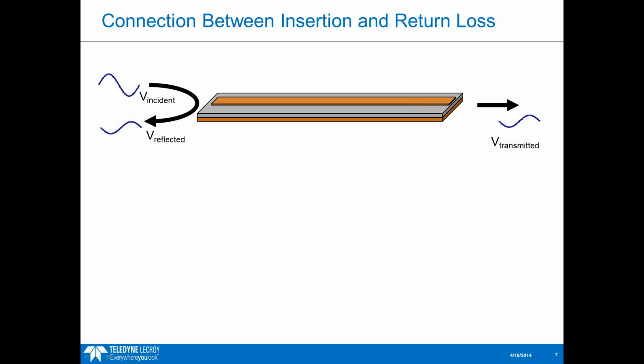Back in my old job, we used to get a lot of questions. One of the favorite applications for this cable tester was measuring cell phone antennas. Apparently, people like to shoot at cell phone antennas out in the desert, and they used their TDR to look for where the bullet hole was in the antenna cable. So you could measure things, and these cables might be 1,000 meters long.